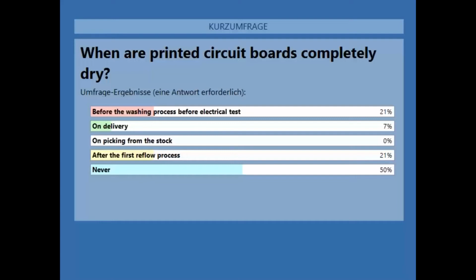So reflow process has a high temperature, but not that long duration that there could be a significant drying effect on the PCB. So we'll see that later. Drying needs time, and reflow process may, of course, dry the surface, but not inside the PCB a lot. And 21% before the washing process, before electrical test. No, at that point, the PCB has seen a lot of different liquid processes, and depending on the surrounding, there is already moisture in the board.